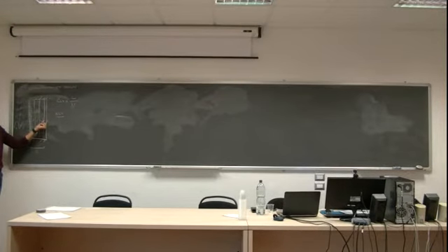The first and the last node are half as thick as the other two. Okay? I strongly recommend you do this. Some people don't do it, and you can face convergence problems at the end.